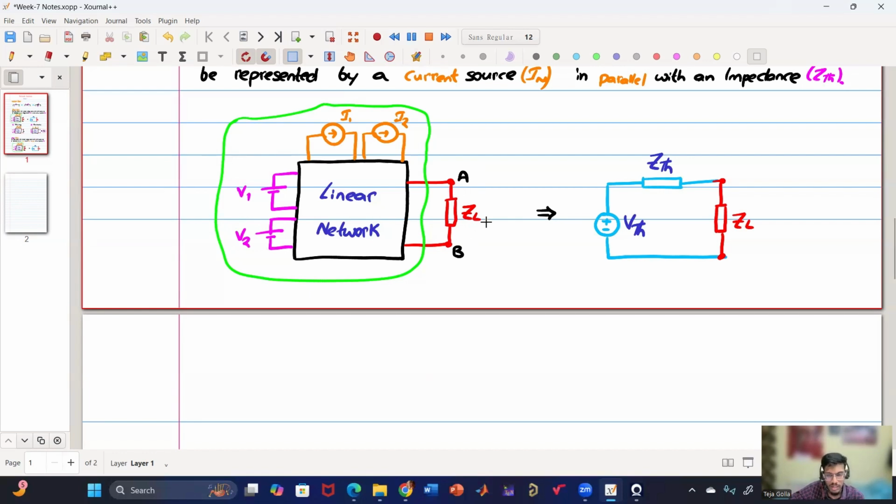will be transferred, right? But if you convert this into the Thevenin equivalent circuit, when you have two impedances in series, there are a few results. Say if this is resistance R, then the load should also be equal to R for maximum power. So then I know that my ZL should be R so that the maximum power can be transferred. Similarly, if this is R plus j omega L, then this should be R minus j omega L for maximum power transfer. So for applications where you want to maximize the power transfer to the load and you have control over the load, you have to find this Thevenin impedance so that you can set the load in such a way that the maximum power can be transferred.